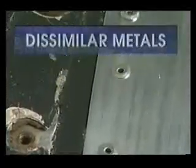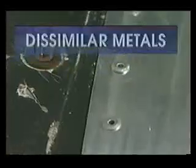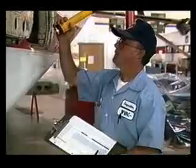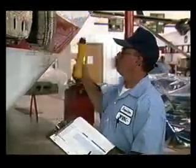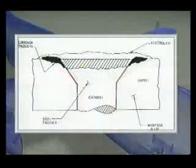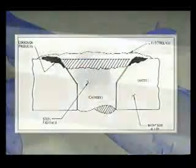Another major area which can lead to increased corrosion is when two dissimilar metals are in contact with each other. When this situation arises, extra care must be taken at every maintenance interval to ensure these metals are protected from electrolytes. Typical of dissimilar metal contact is the case of stainless steel fasteners attached to aluminum skin. If dissimilar metals cannot be insulated from each other by paint or sealant, corrosion can only be prevented by carefully maintaining the integrity of the paint on both metals to eliminate electrolyte contact.